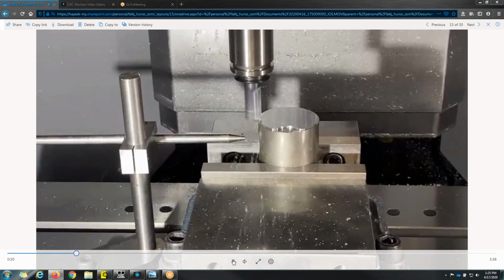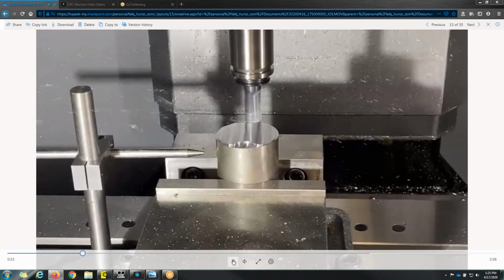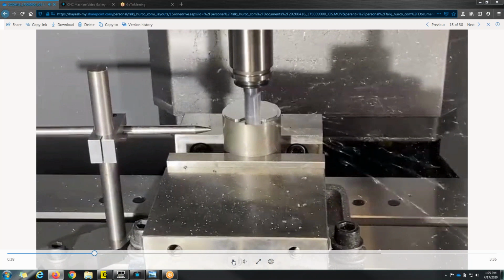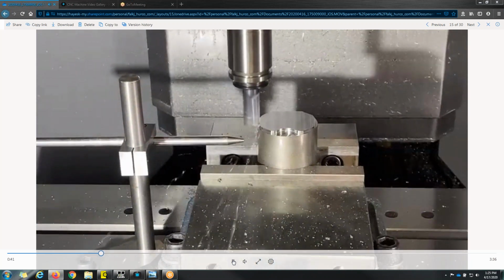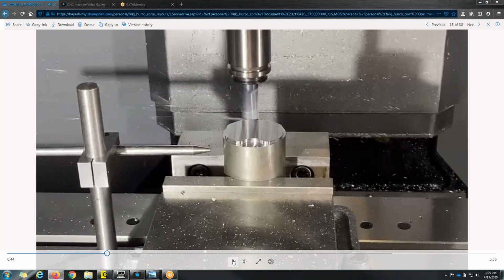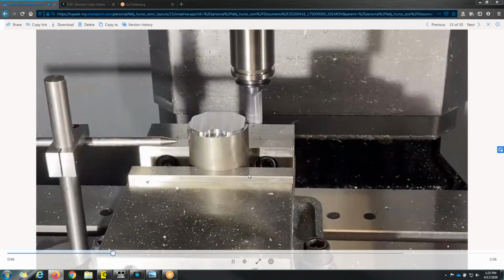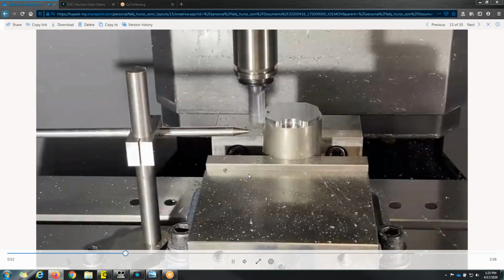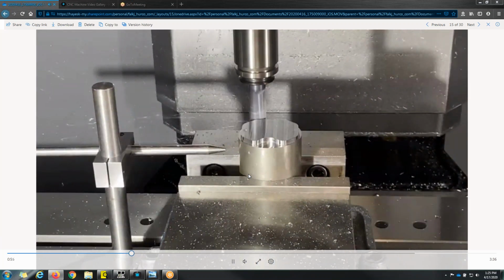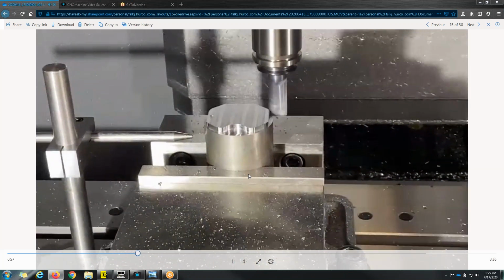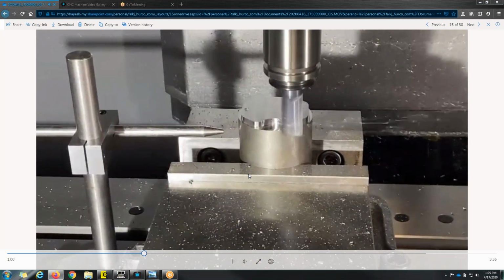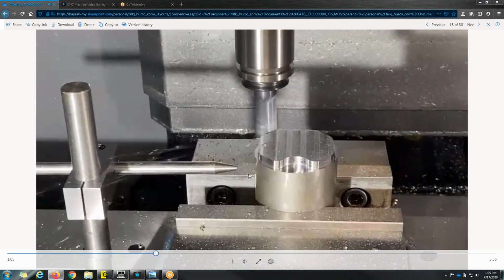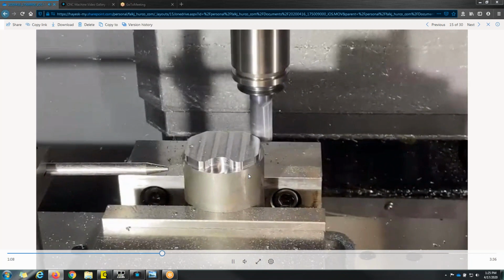One of the main times I like to use this is if I'm cutting a part and maybe my fixturing isn't quite as rigid as it could be. Take for example this part here, I did mill a couple flats into the material, so I probably got a pretty decent hold on it. But if my fixturing wasn't as rigid as it should be, I like this style of motion because rather than coming in and putting a lot of side load on to take a cut, sit down and take another cut, most of my pressure is going down in the Z axis.